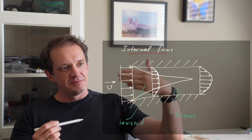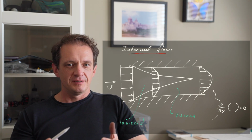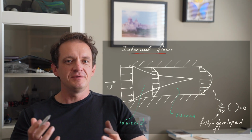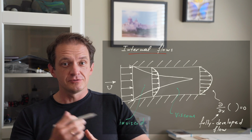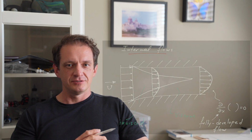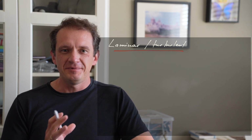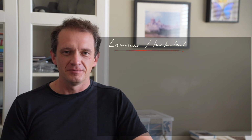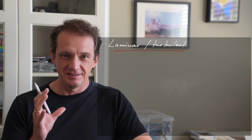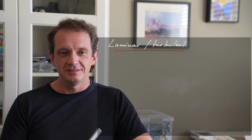By the way, some distance from the entrance, the flow becomes fully developed, so there are no changes of any parameters in the x direction. That's an important condition that can also be used to simplify the governing equations. The laminar or turbulent flow classification is a challenge. The primary challenge is in predicting the details of the turbulent flow, but actually classifying the flows into laminar or turbulent, the distinction itself is not very difficult.